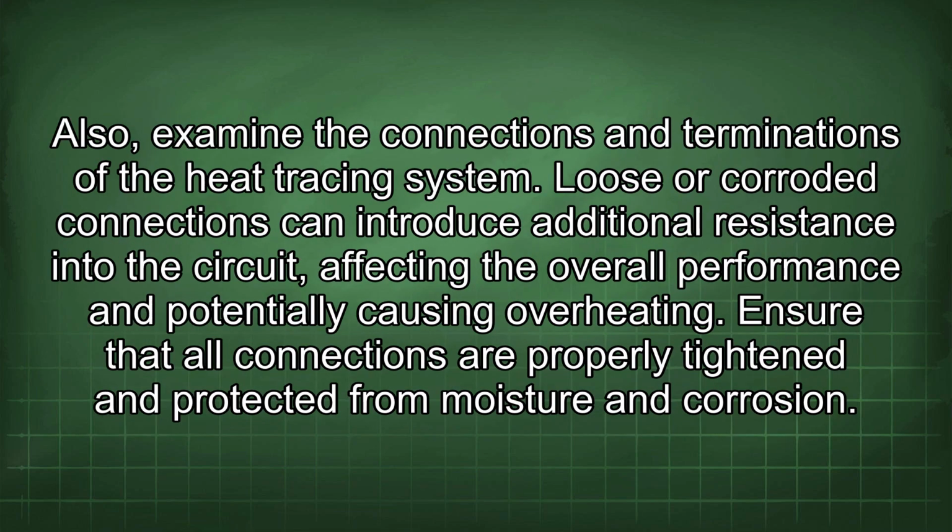Also examine the connections and terminations of the heat tracing system. Loose or corroded connections can introduce additional resistance into the circuit, affecting the overall performance and potentially causing overheating. Ensure that all connections are properly tightened and protected from moisture and corrosion.